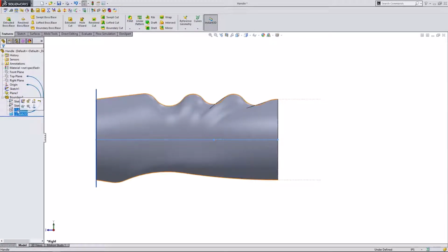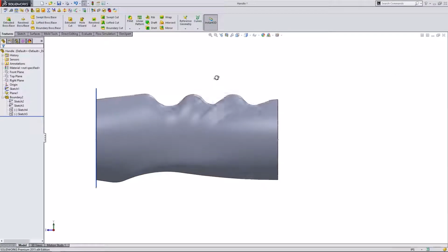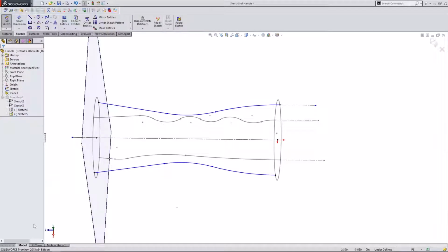So what I mean by that is if I show where the contours are, these finger points, they're stretching the material a lot in this area. So if I change my two curves to be closer to this point over here, the material itself is going to stretch less and less. So that's something that I've learned from the geometry of this part. I'm going to show you what that means right now.